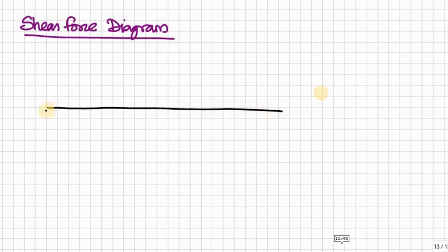Now the shear force diagram. Now draw the ABC line, that is the beam line. So at support A we have 98.70 reaction, upward reaction. Therefore at the top you have to mark the shear here, and for the UDL it gradually comes down to 81.3.